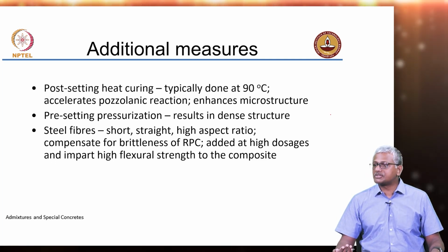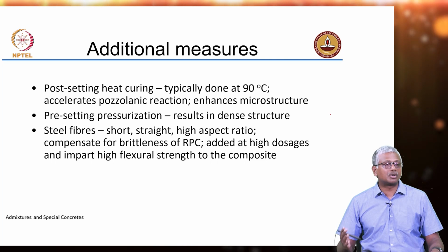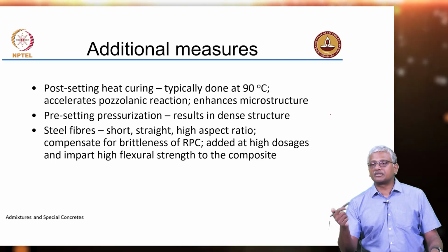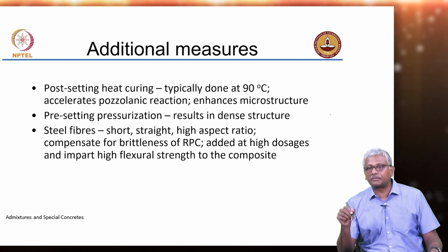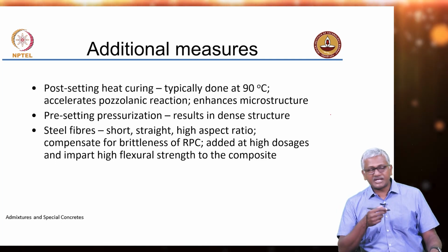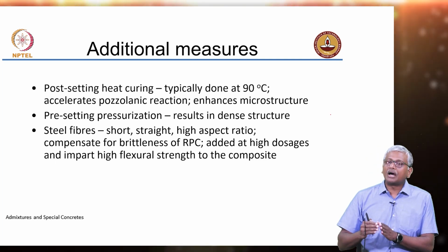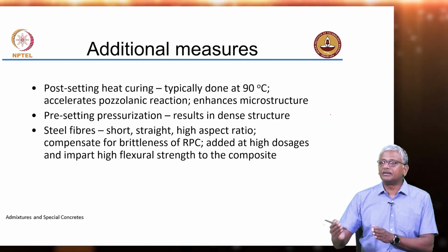How do we define flexural strength of concrete? We define it as modulus of rupture. Even when you use fibers, modulus of rupture is basically seen whenever the first crack appears, right. You do not change that at all when you use fibers. But beyond that point, how soon does failure happen is governed by the use of fibers.